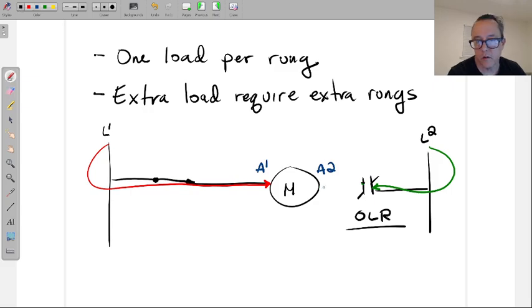There's no stopping of the motor. It de-energizes the coil. No more inside magnet. The magnet is now no longer, and so the contacts just let go. And that's what stops the motor. So that's why technically when you press start on the motor, you didn't start the motor. All you did was energize A1. You energized the coil. From there, hopefully contacts are closing and there's power going through those contacts for the motor. If the power's not there going through the contacts to the motor, the motor's still not going to start, even though you're pressing start and everything seems like it's supposed to be working.